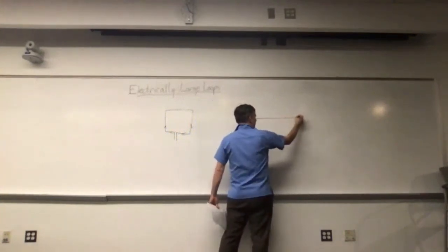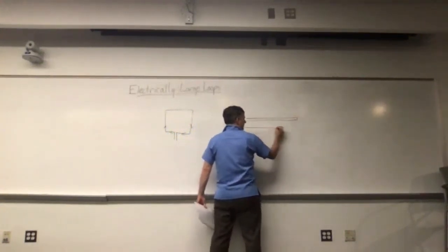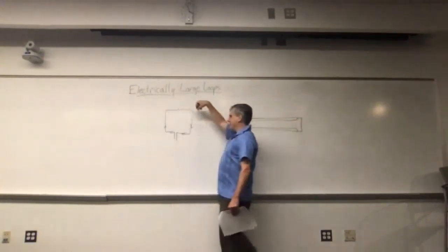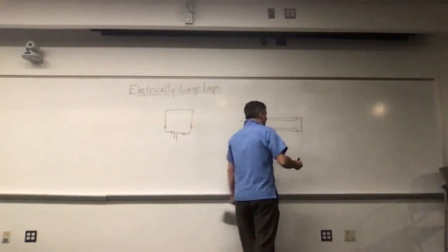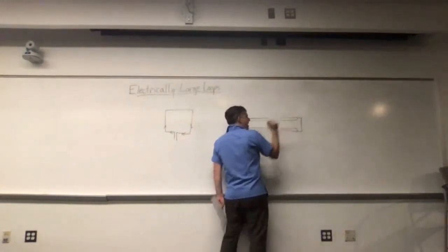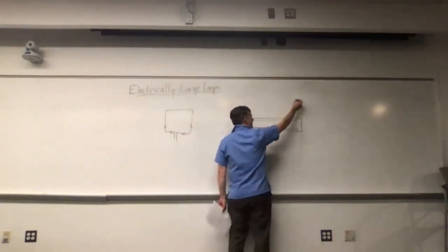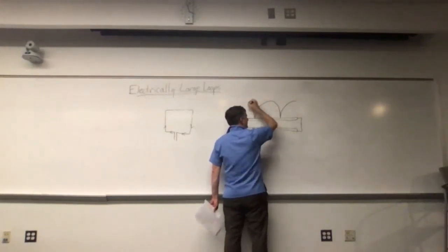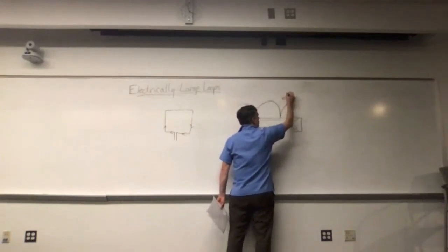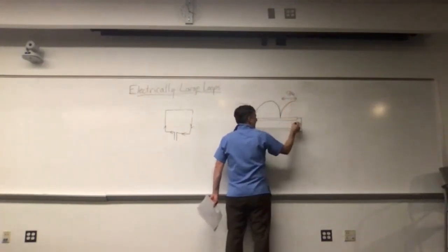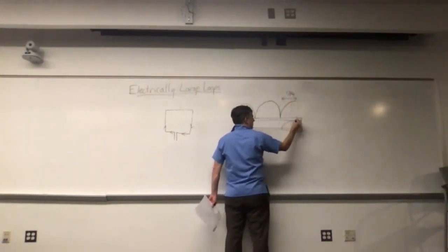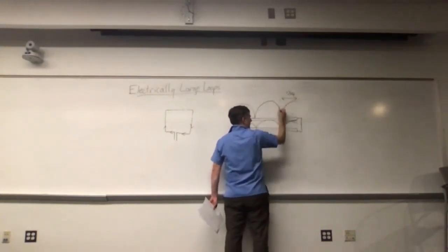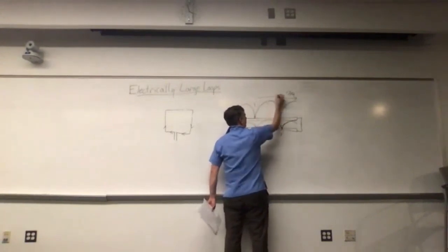Let's say I have a transmission line that is short-circuited, because I have an electrical path of conductor all the way around. I short-circuit the path. Now my current is going to be at a maximum here, and the standing wave is going to proceed like this, where this is a quarter wavelength from the end. I have the exact same pattern down here. Quarter wavelength. This is a half wavelength.